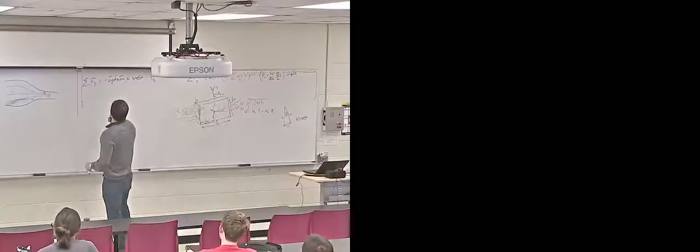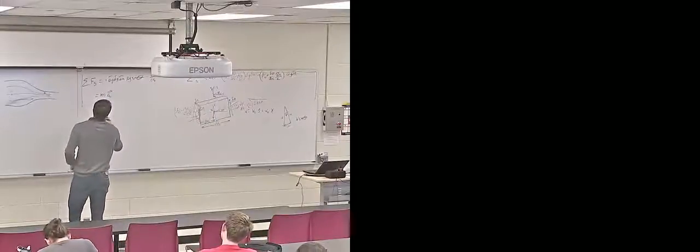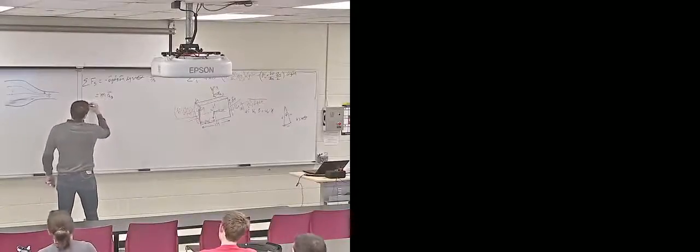Minus. All right, now the sum of the forces is going to be equal to what? By Newton, ma, right? And we forgot a g here, that's the weight. Sum of forces equals ma. Well, since it's all along the streamline, m a_s. And m is going to be equal to rho dy ds dn, and a is simply equal to, as we wrote it up there right before I erased it, V dV ds. Yeah?